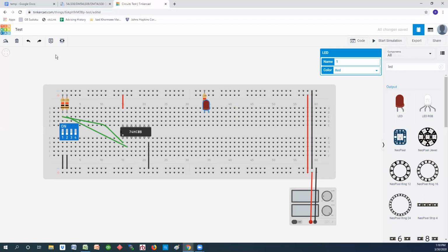So what I'm going to do is take a piece of wire from the output. Remember pin 3 is the output, and I'm going to take that to the pin of the LED. So if everything works, we should be able to have this LED turn on when we do the simulation. If you remember, just like the electrical side, the analog side, if you want to figure out whether this is working or not, you just start initializing, and you see both of these switches are down. Remember, this circuit is open, so this is directly connected to 5 volts.